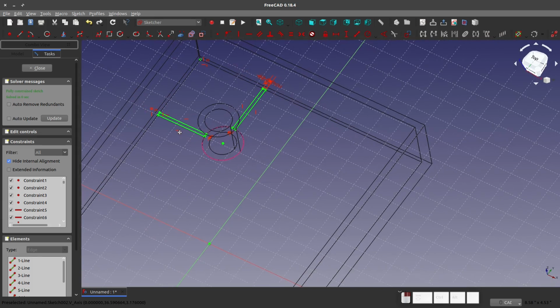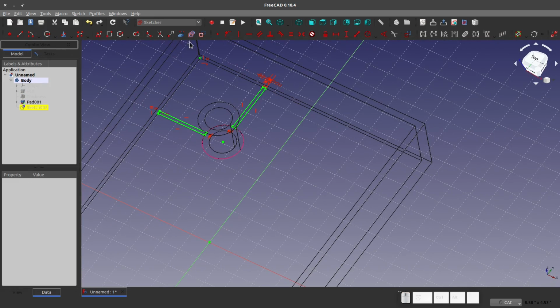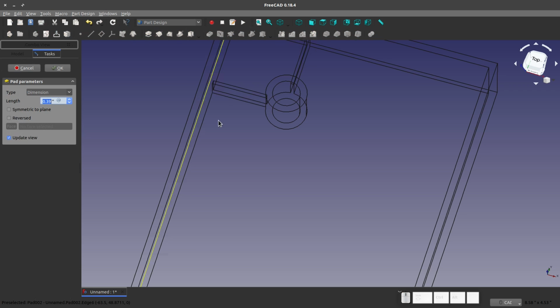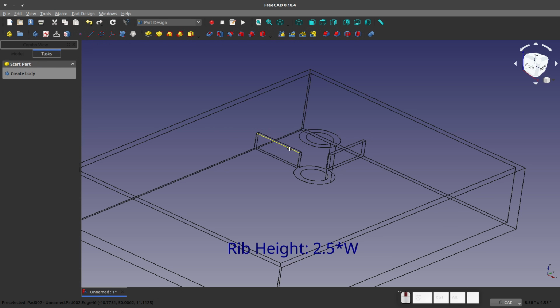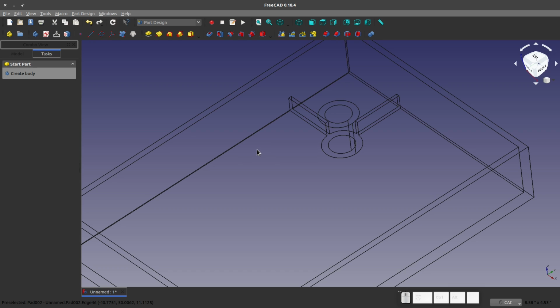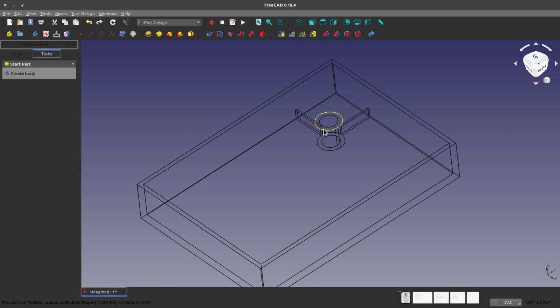And let's extrude that. So we're going to say tasks, close, we're going to extrude. And then the next question is, how high should ribs be? Not dependent on your material. A rib should be 2.5 times your wall thickness, max, right? So that's as tall as the ribs can be and still have some certainty that they won't start voids, sinks, ejection issues, or anything else.